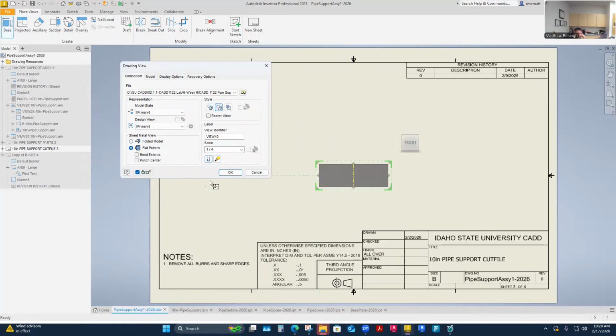And you can scale this the same way. You might work for a company where it's really critical that all your cut files are at the same scale, because the machine is going to depend on those scales being the same, and you really pay attention to that. It's really common for me, whatever parts I put on every sheet, to have them all at the same scale.